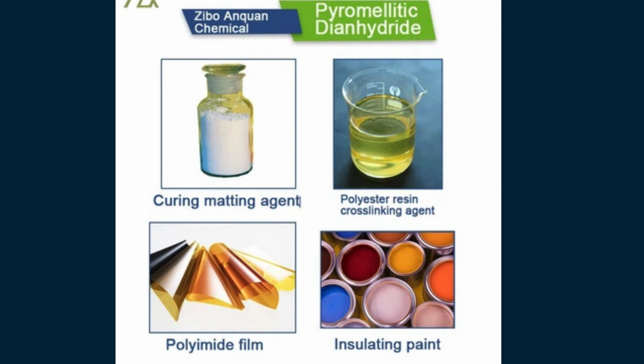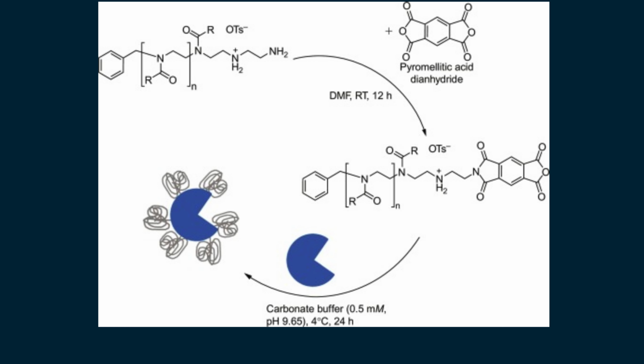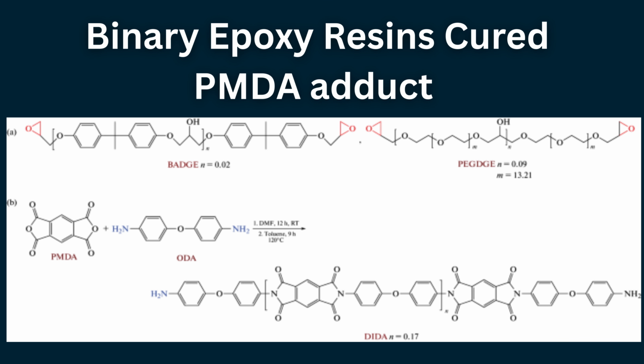However, PMDA is insoluble in epoxy resins at room temperature and reacts rapidly once dissolved, making processing challenging. Several techniques are used to incorporate PMDA into epoxy formulations, including preparation of glycol adducts, solvent solutions, or suspensions in the resin. These systems are commonly used in high-temperature adhesive films.